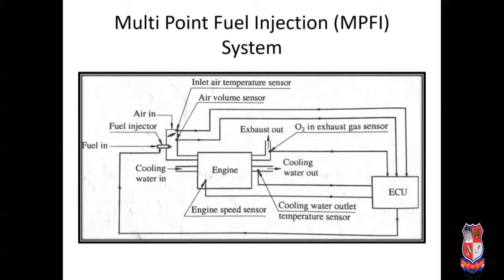Again, here starting is very easy, and in a multi-cylinder engine, the same air fuel ratio will be applied to all cylinders by using the MPFI system. Okay, and the last advantage is that as the required air fuel ratio is supplied at different conditions, exhaust emission will be lower and more power is developed.